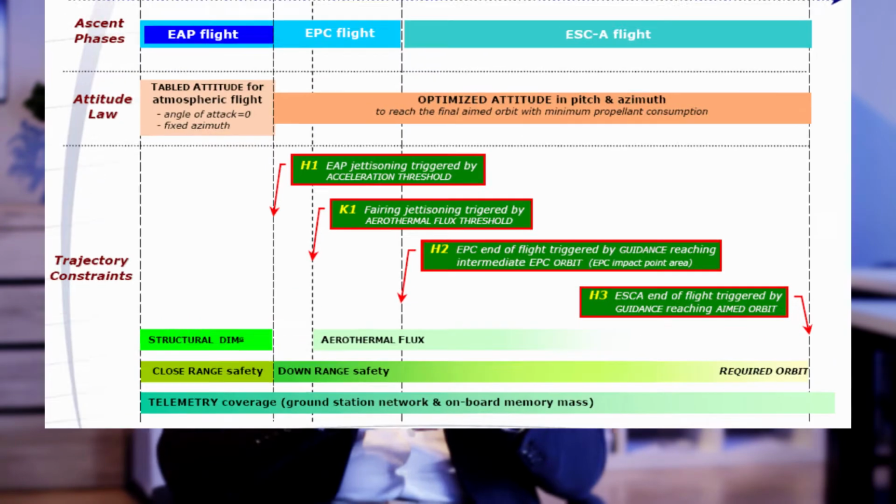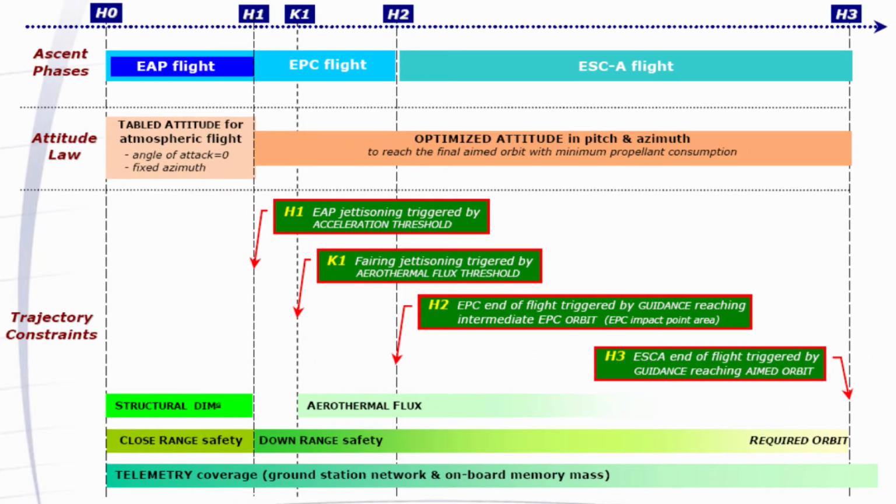And so the Ariane 5 last stage, through attitude control thrusters, can orient in different directions depending on the needs of the launcher. Then they can be slow spin separated, high spin separated, or three-axis stabilized, depending on what is the need of the customer.